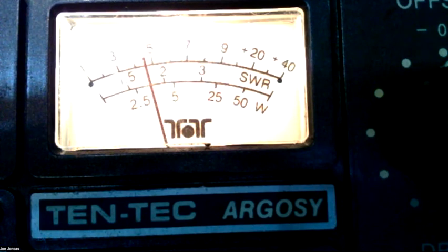And if you're running a 100 amp hour battery, that means if you're transmitting nonstop CW for 5 hours, your battery will be totally dead. If you drop down to 5 watts, and I don't know what that draws, very, very little, that battery will last many times longer. And most of the time you should be able to get away with it. You might kick up to 50 to 100 watts to get communications established. Once you got it, drop it down. And most likely the guy's going to still be able to hear you.